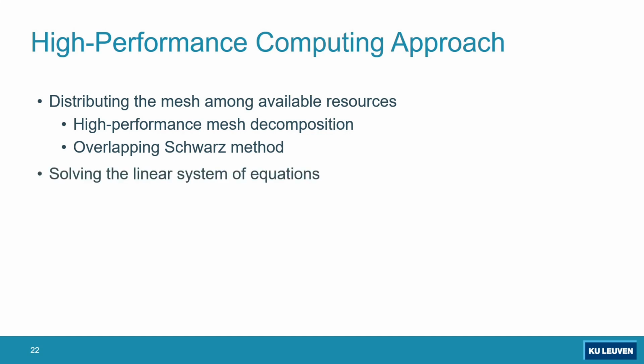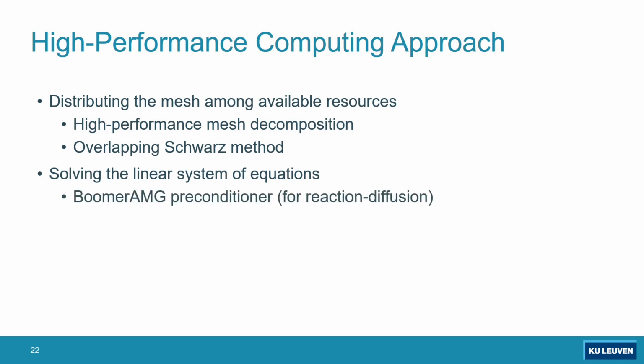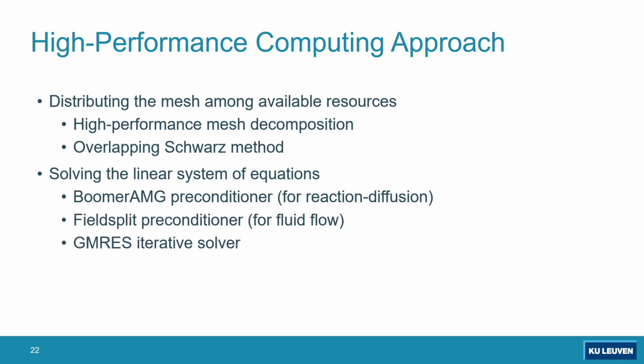And then another aspect is solving the linear system derived from the finite element formulation. In order to do that, we had a set of very effective preconditioners available in PETSc, such as BoomerAMG, available from the Hypre package for reaction diffusion systems, field split preconditioner for fluid flow, as well as a set of iterative solvers such as GMRES.